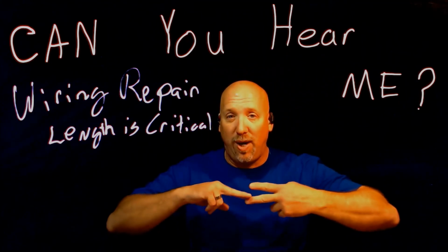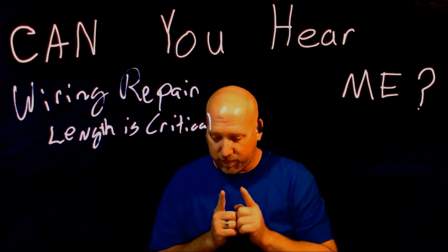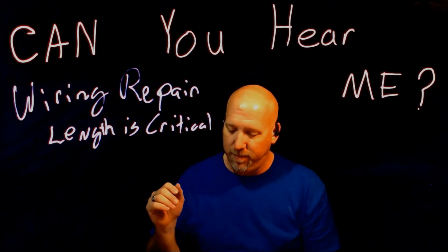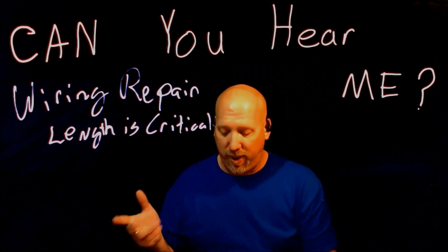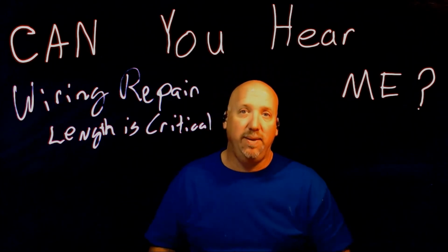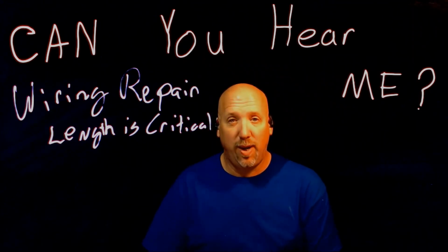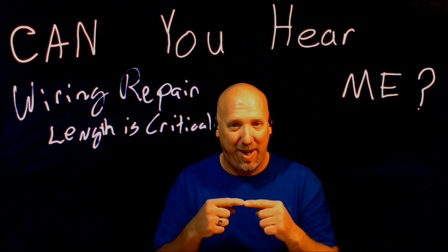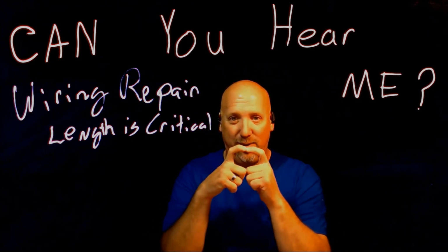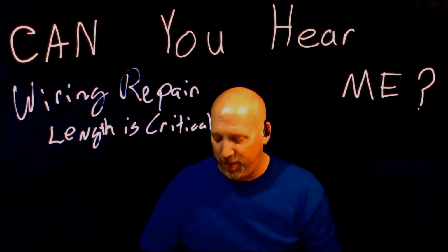Maintain the original wire twisting. Remember about 7 to 9 twists per foot or something like that. When relevant, 1 twist per inch is about standard for most 2-wire networks. I've seen them twisted more than that. So maintain the original wire twisting. Remember, when you're making a splice, especially soldering, you're getting that hard joint there, and your wire may not bend in that splice. So be aware of that when you're splicing this right here.